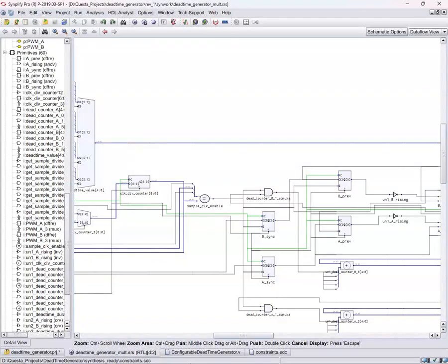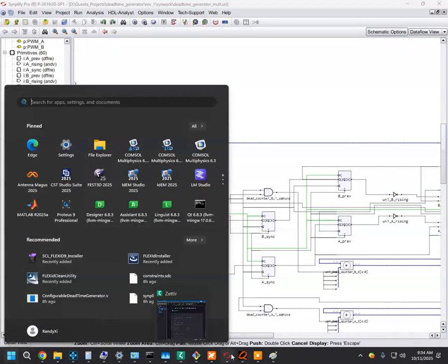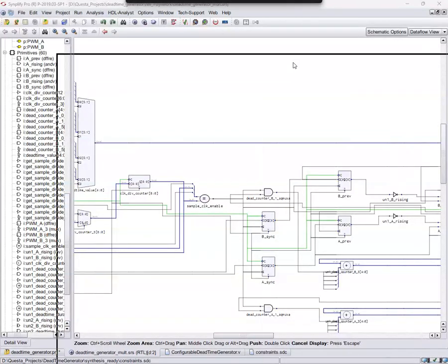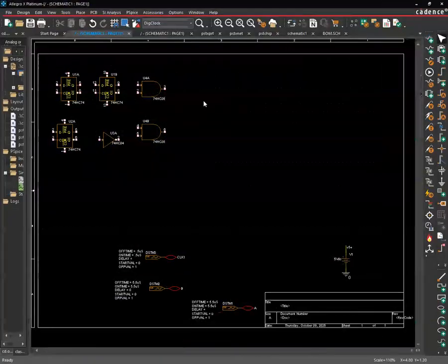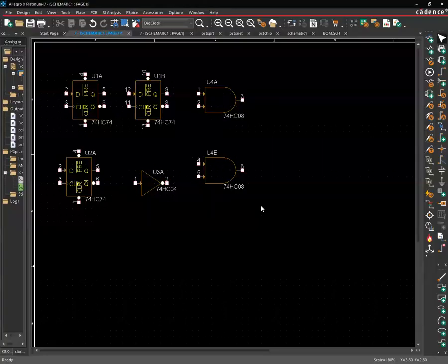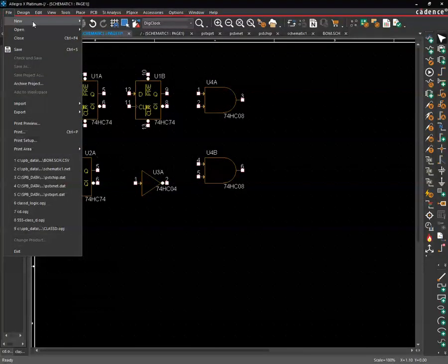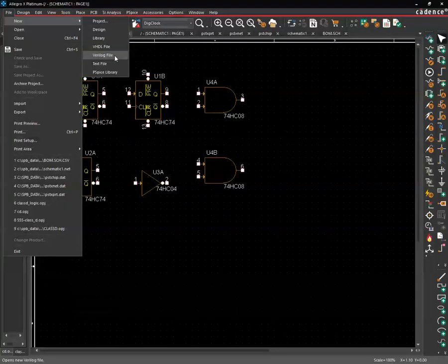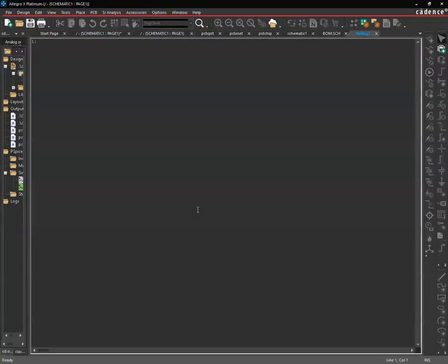What I'm going to do in Cadence now, before I go into Linux to do anything, is manually build all the logic over here from the schematic. Once I do that, we could do a Verilog file here, so I will do a Verilog and a test bench, run every single thing here, and then I will do the schematic, the logic itself.